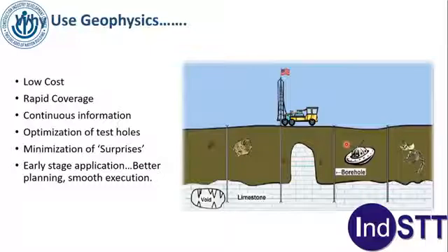Seismic tomography. This is the image of seismic tomography where there is a big void. This was 85 by 60 meters. It was a tunnel project. Depth is around 200 meters. This is 215 meters here. And this was a big void there. So anyway, the idea is to tell that different techniques are available to find out boulders, cavities, etc.